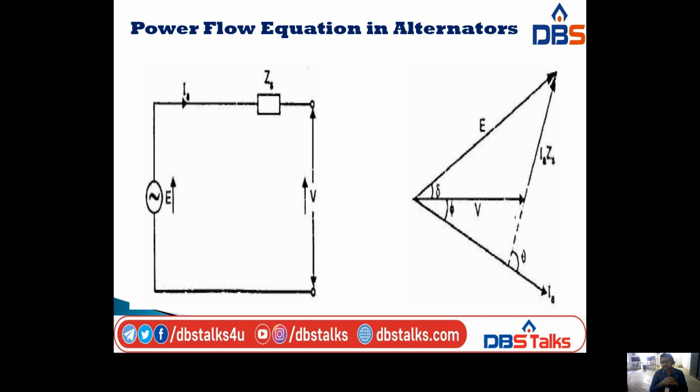Here it is connected to the armature current also, because the voltage drop consists of two parameters: one is armature current and another one is synchronous impedance. That's why I indicated it with dotted lines, and the angle between these two is theta, the internal angle. This is the phasor diagram and circuit arrangement for the derivation of the power flow equation in a cylindrical rotor alternator.